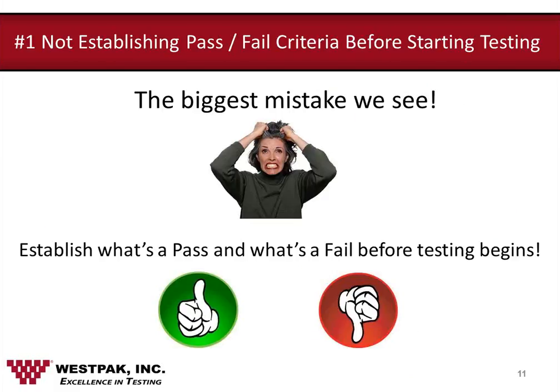The number one mistake we see people make when they're designing a package is not establishing pass-fail criteria prior to the start of testing. You'd be surprised how many people come in and say, just run the test, and you say, well, do you have any pass-fail criteria? And they go, no, we just want to run the test, so go ahead and run it.